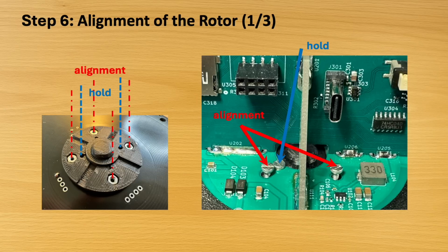This plate is extended with an additional disc into which 4 M2 nuts are inserted. The holes marked with the blue lines are used for the mounting screws, while the nuts marked with the red lines are used for fine adjustment. Please compare the left and the right photo.